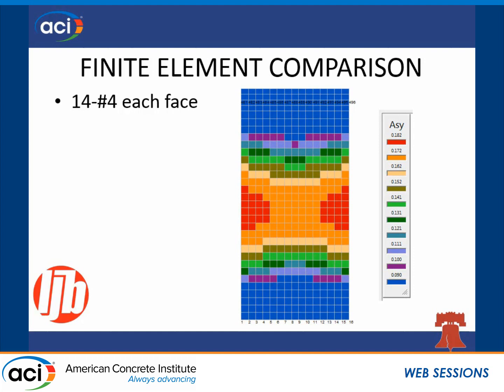The reason it's doing that is because it's not taking all the limitations, or the things that we neglected, I should say, in the 318 procedure. You still have the contribution of the negative moment region for the parapet at the top. So you've got the contribution from the negative moment that reduces the positive moment at the parapet, and some of the other limitations on the strength and stiffness of the concrete. You'll also notice that the finite element model tells us a lot about that free edge of the panel and how that compressive force is actually more into the internal portion of the panel.